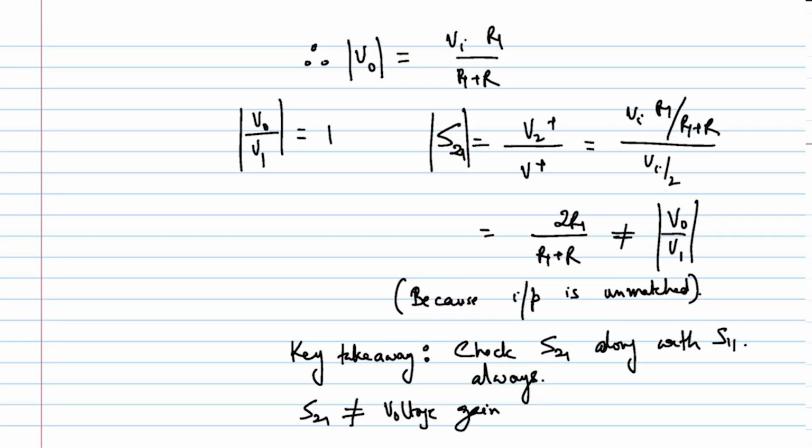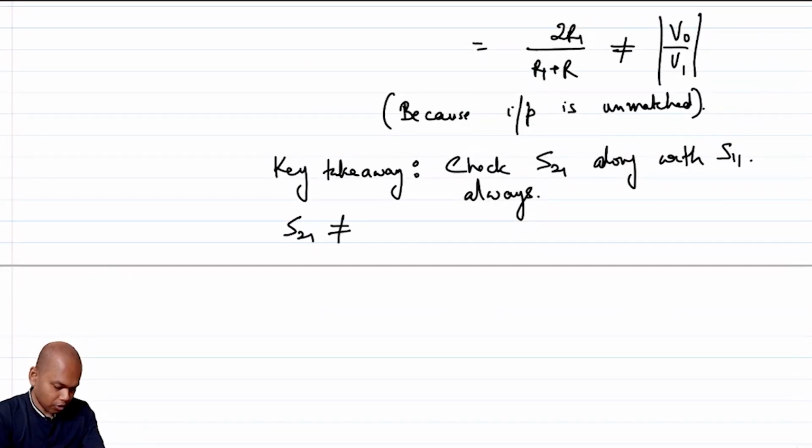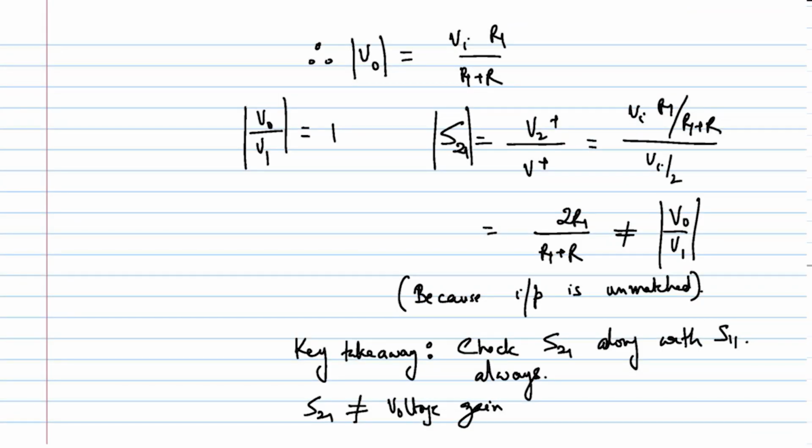And another key takeaway is S21 is not equal to voltage gain, right? It is some special condition under which S21 equates to voltage gain. Okay, let's stop here.